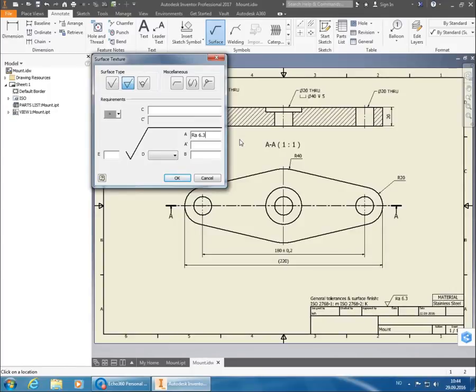It means that they can have quite a lot of speed on their tools when they are machining it. So it's still a very nice surface to look at and touch. You won't really feel any ridges or anything. So if you go lower than 6.3, then you're putting limitations to the speed of the machining process. So 6.3 is also a nice, even choice to use when you're not quite sure what you're going to have.